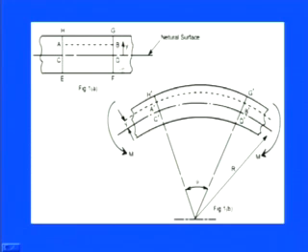You can see the first diagram here on the screen, where we are taking these two elements in which the two lines EH and GF are simply parallel. As we discussed already in the previous chapter, the middle section passing through the beam is the neutral surface, which is nothing but our neutral axis. We want to focus on an element, let us say AB, at a distance y from the neutral axis, and how the fibers will behave when it is subjected to a bending moment. That is our prime focus.